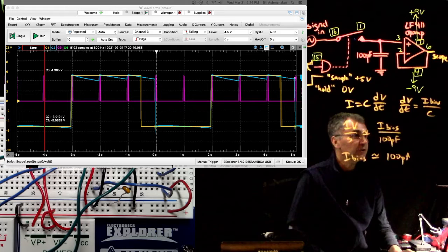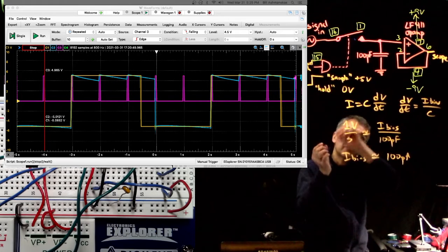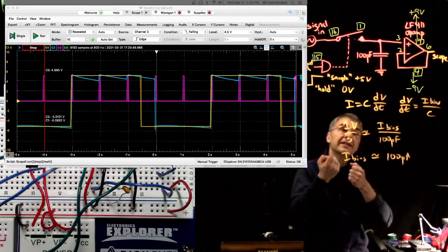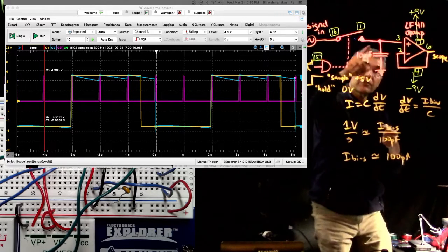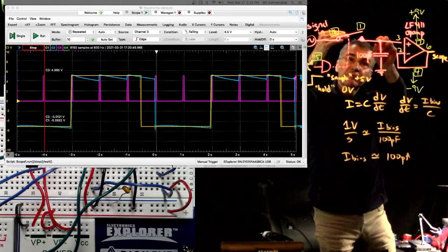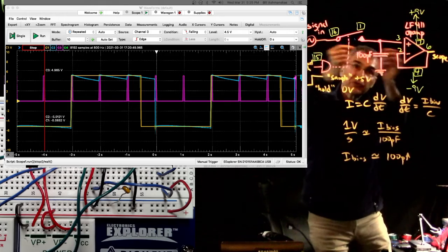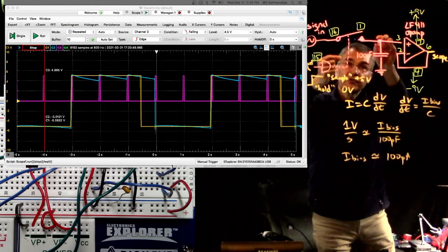So you see, we were grabbing the sine wave. We want to save the sine wave long enough to look at it, so we use the capacitor to keep it. You close the switch, and charge flows onto the capacitor or off the capacitor, so this voltage is the same as this voltage.